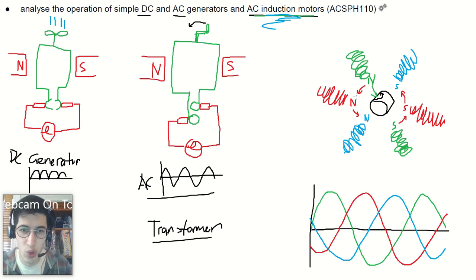Then as that north dies down, right? As that north dies down and this north increases in strength, this position here, sensing the disappearing north, is going to create its own magnetic fields in the same direction as this north was producing. It's going to try and bring them back. So now it's going to be producing magnetic flux in the other direction, and it's going to have its own little south pole up here.